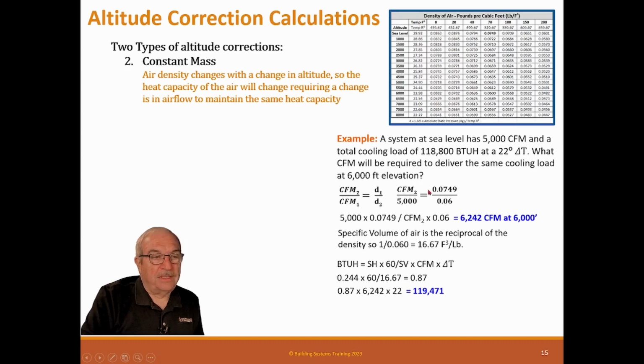Remember, in these HVAC calculations, they are not perfect because they're based upon constant factors that don't have a lot of decimal places. So there is some kind of room in these calculations. So don't ever expect your calculation to be perfect. Instead of using those factors, you can use the real number, and you can get a lot closer. But even then, there's too many constants and too many assumptions made in all these calculations to be perfect. So we know they're close, we're good to go.